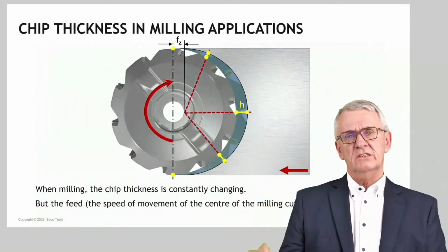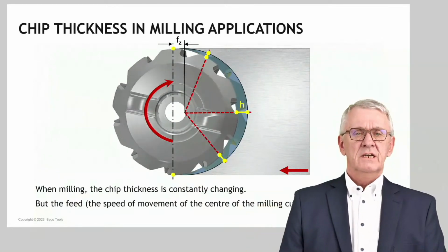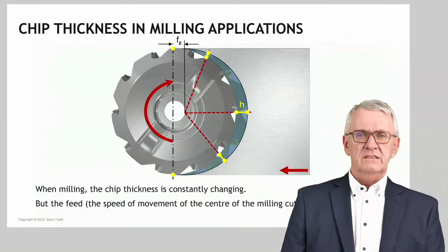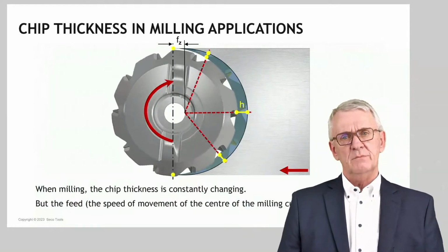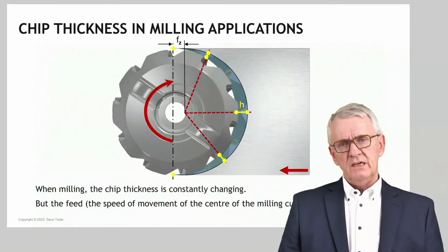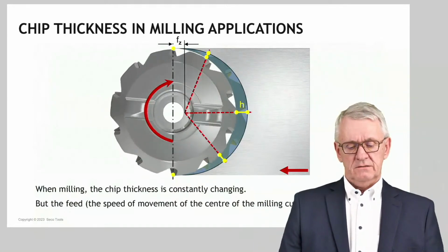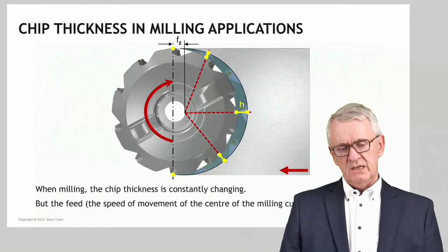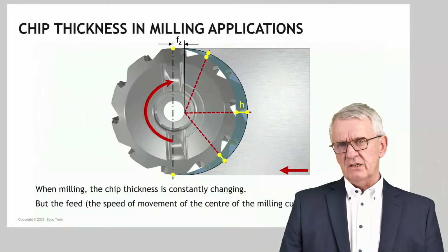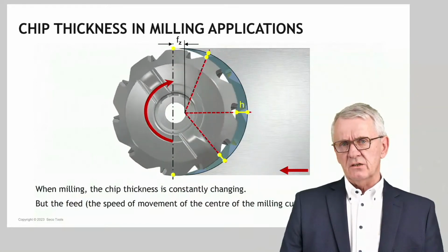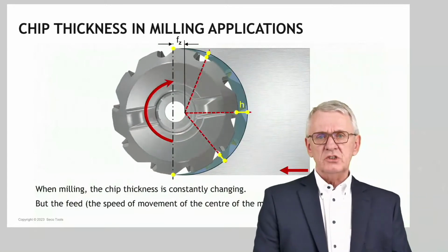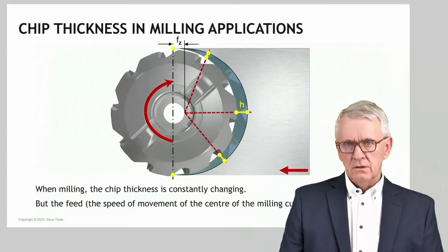And then the cutting edge, as it continues cutting, the chip thickness is going back to 0, perhaps again too thin, and think of heat. And that's the dilemma with which we are confronted here now. How do we make it happen? What I said a couple of slides ago: the designer of a milling cutter thinks about physical phenomena, they think about chip thicknesses.